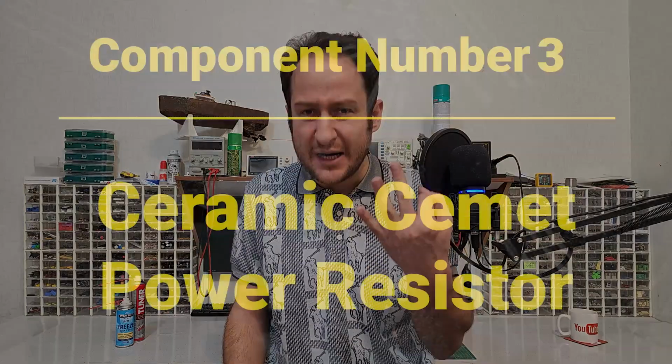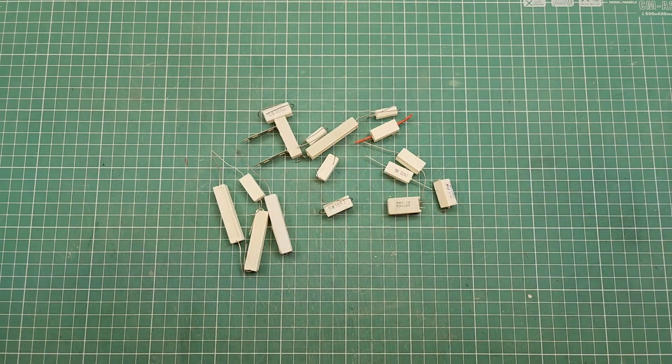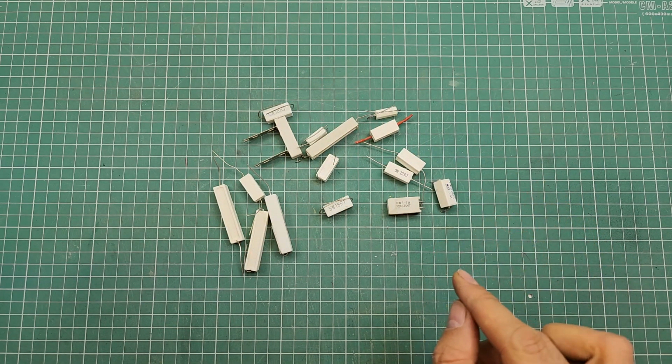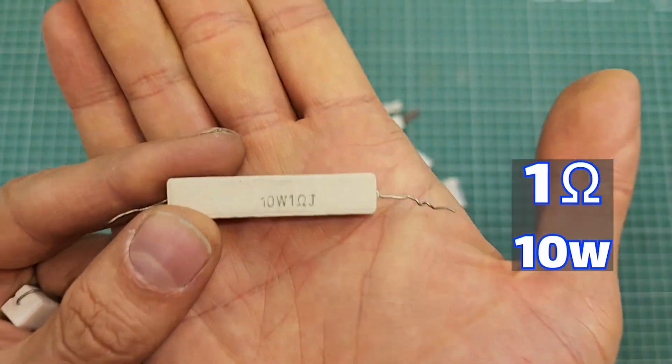Component number 3, ceramic cement power resistors. Ceramic cement power resistors are a type of resistor that can handle extremely high powers and currents. How much current they can handle is determined by their power rating and their resistance value. Here are some examples of ceramic cement power resistors. The resistance and power rating of each one is printed right on it. For example, this one is a 1 ohm 10 watt resistor.